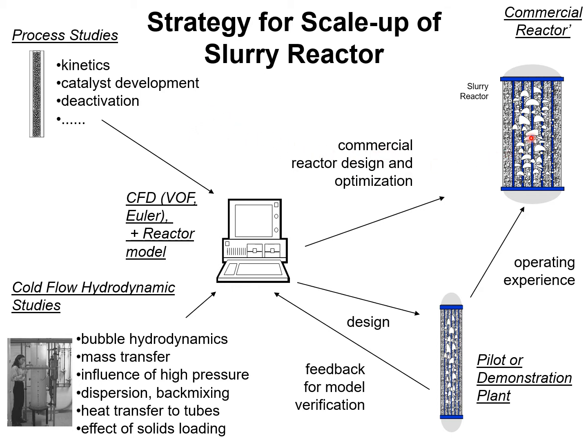The scale-up strategy involves process studies on, say, a micro reactor scale to study the kinetics, catalyst deactivation, and catalyst preparation. In addition, we need to understand the hydrodynamics of the bubble column slurry reactor.